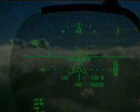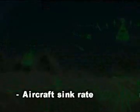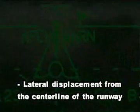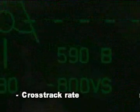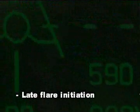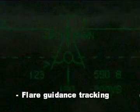The flare monitor evaluates aircraft sink rate, lateral displacement from the center line of the runway, pitch rate, airspeed error, cross-track rate, late flare initiation, flare guidance tracking, roll angle, touchdown distance from the threshold, long landing.